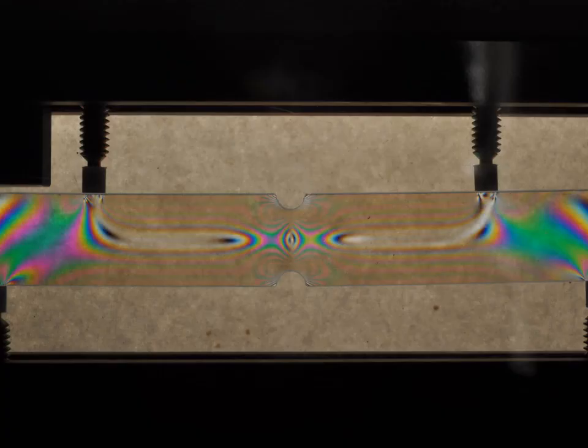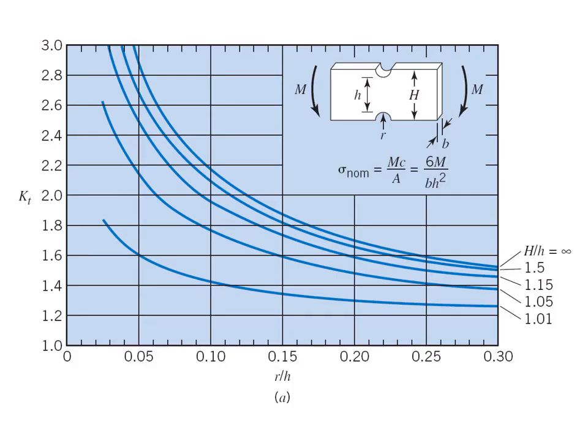So here's another image from the SLR of a sample where we now have these 2 notches. With any of these specimens, one of the things we mentioned that we're going to need to do in this lab is to take measurements and know the overall dimensions. So we can take the information we can see here and the known dimensions and location of these loads. For our specimen, we have those 2 notches. We have the known dimensions: thickness, the height, the distance between those 2 notches, and the radius of the notches, which we can measure.